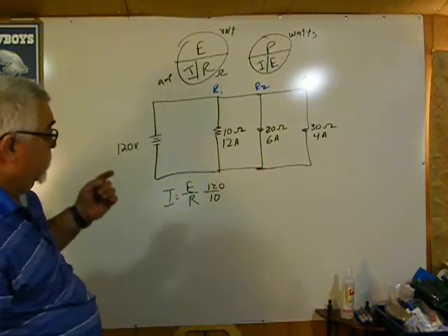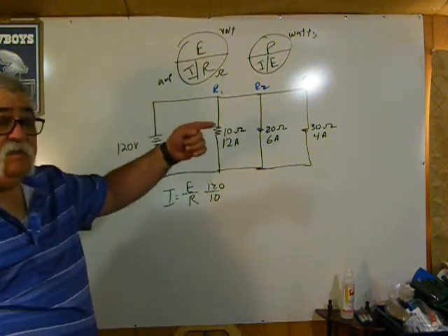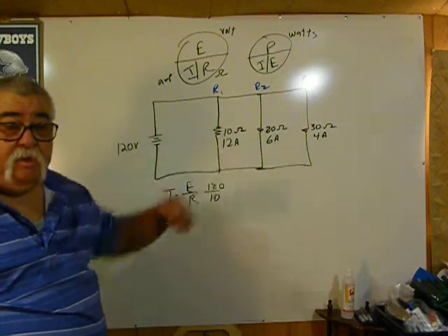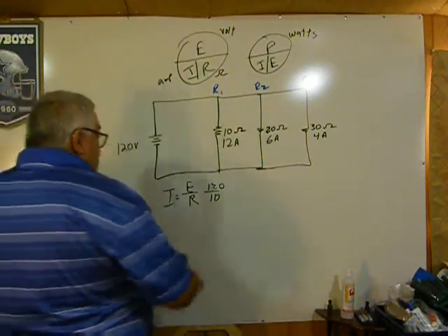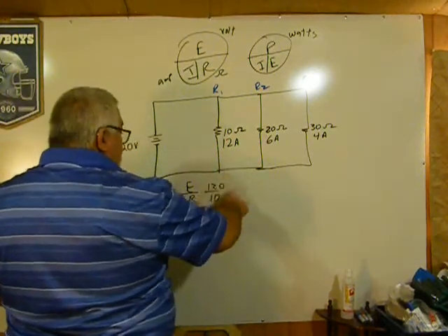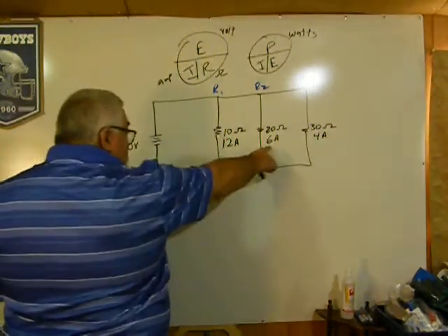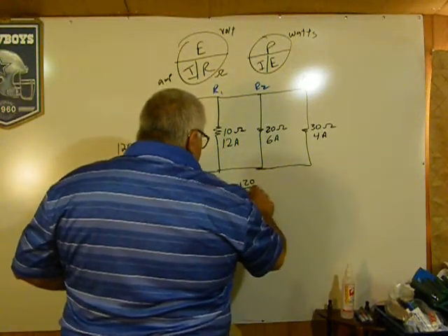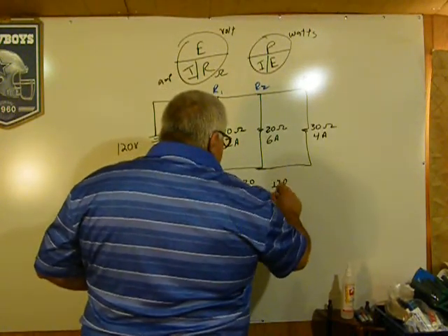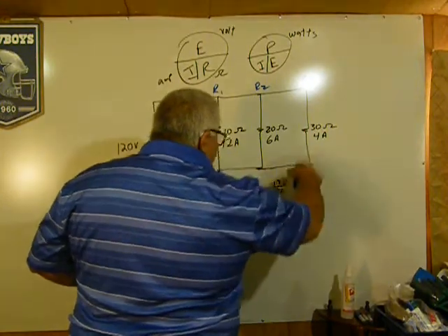As you notice, as my resistance increased, my amperage decreased. For each branch it's just the simple formula, and I used it for all: 120 divided by 20, and 120 divided by 30. And that's why I got the last one.